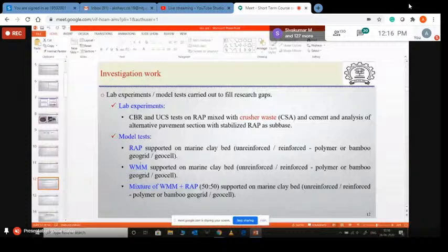And then just over the geotextile separator we have used polymer geogrid, and then polymer geocell, and a combination, and tried to find out how the load carrying capacity is increased with respect to the unreinforced material. And we have found a substantial increment in load carrying capacity.